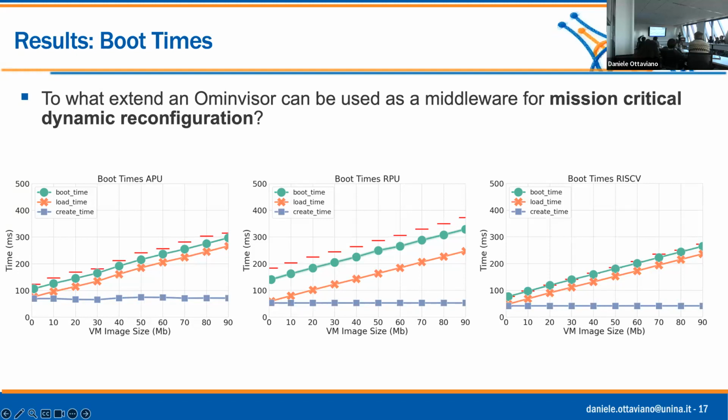Good question. What do you consider boot time, since you're not starting operating systems or anything here? When are you done with boot? Yeah, the boot time is the first instruction of the main of a bare metal application. The first instruction just takes a value of a system timer, and we take the difference between this time and the time when I started the process. So there's always some startup code that gets executed before the main. So that's what you're showing in the end.